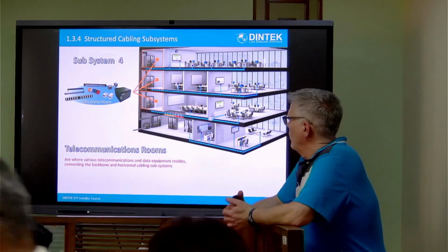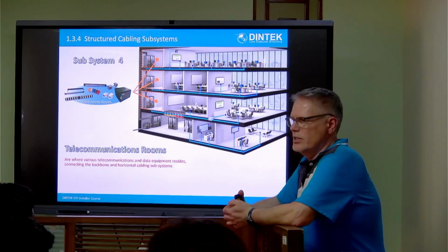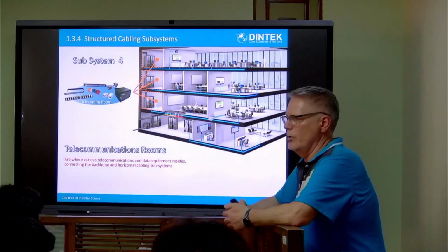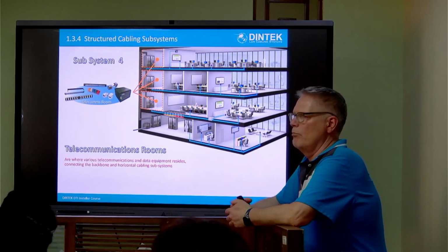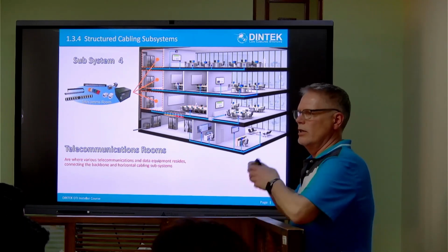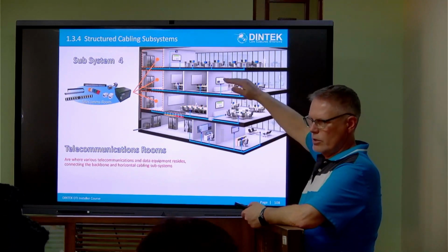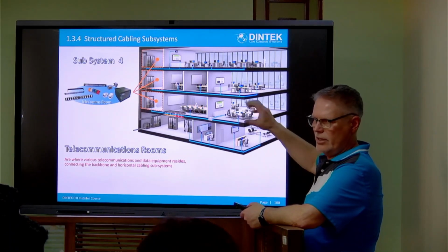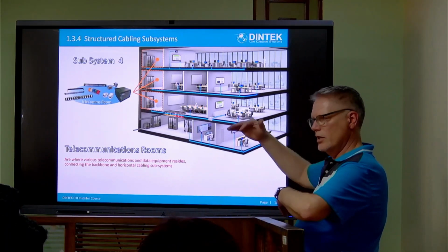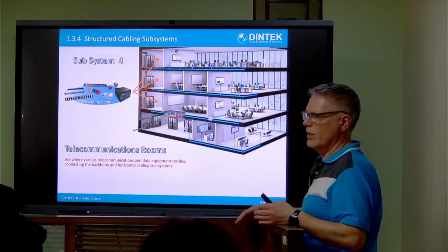And so, when we talk about structured cabling, you don't necessarily have to have a telecommunications room. But if you do have a network where they designate the floor distributor is going in the telecommunications room, that's when you come to our structured cabling system, and standards will tell you minimum sizing for your room, heights of doors, all that sort of thing.